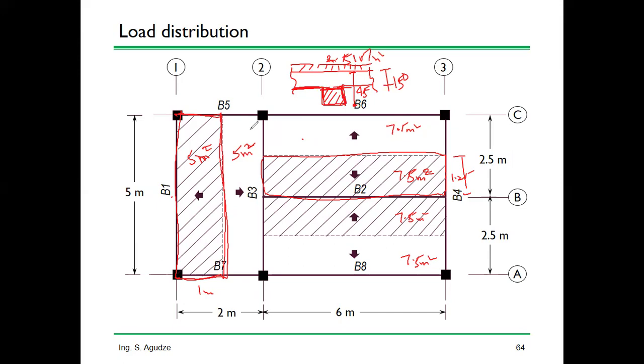If you take the full beam again, it's like you have done a double calculation, right? So you don't do it that way. Once you have taken the slab all across, if you are dealing with a beam, you are just dealing with this drop, not the full 450 beam again. Good. So let's quickly calculate the design load, which will now multiply with these areas. And then we draw the line diagram and we are good to go.